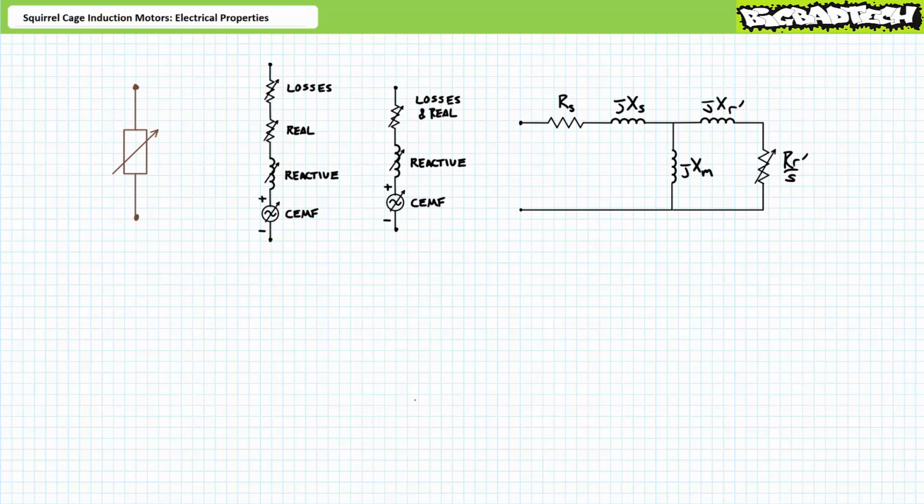You'd think there'd be a simple formula to account for the magnitude of each component depending upon the motor's operational state, but there isn't. The real component slopes gently downwards as a function of rotational speed, slopes rapidly upwards as the motor approaches peak power, then nosedives as it approaches the no-load speed. The reactive component does something totally different.